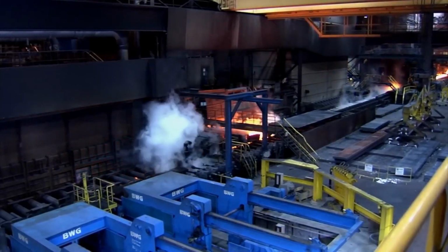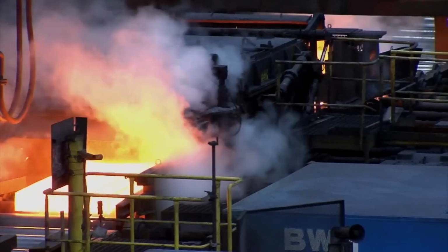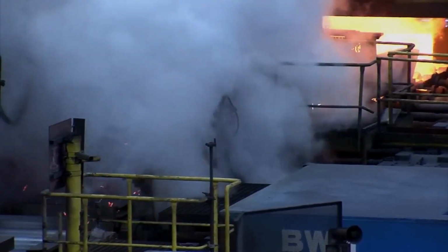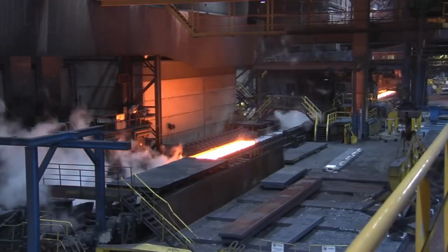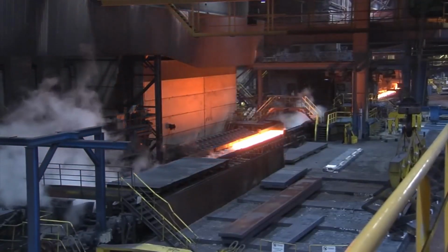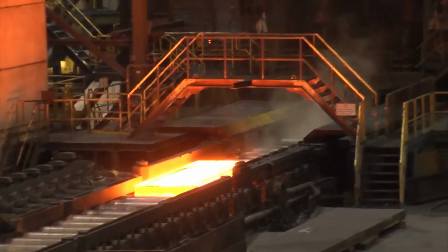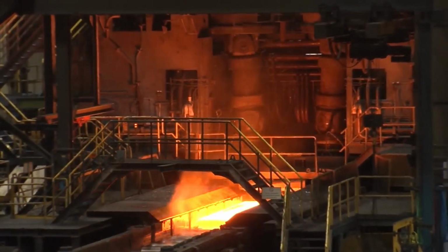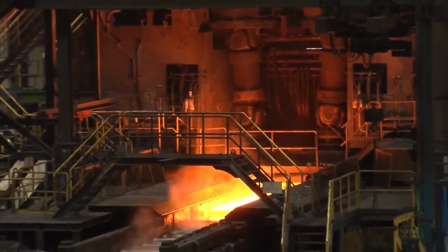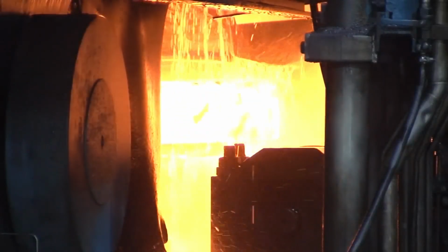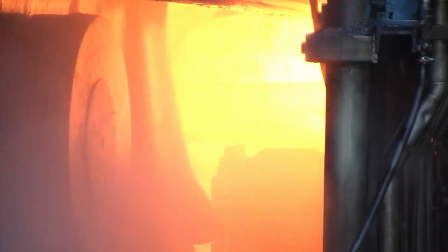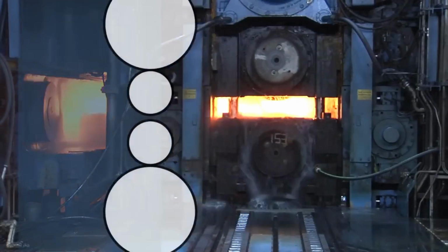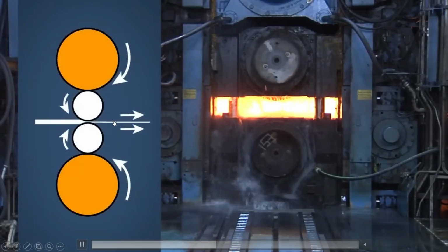Everyone has to understand, whenever a material is red and the metal is being worked on, in most cases this temperature is called the recrystallization temperature. Recrystallization temperature means the crystal structures, the crystal lattices inside the materials, which are FCC, BCC, have not formed properly yet. They are in the process of forming. So if you keep the temperature above the recrystallization temperature but below the melting point, this material is being squeezed between the mills.